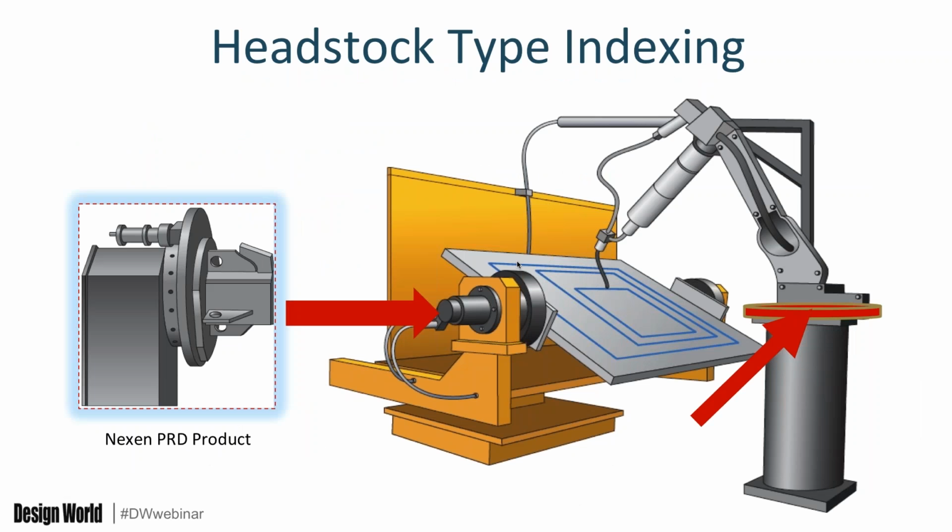In a perpendicular orientation, it's very common for what they would describe as a headstock application. And here, in a typical headstock application, it's an automated welding. The indexers can be used in the headstock or the tailstock. So in this illustration, it would be either at the left or the right, or a combination of two, using electronic timing to put it together. The bearing consideration is flexible, and the mounting orientation and access through the output center are very important factors.